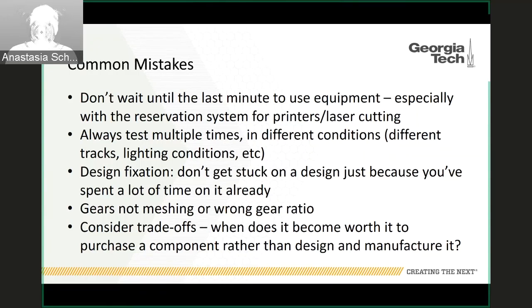And then finally, one that I really like to address is that you should always consider the trade-offs. When is it worth it to purchase a component rather than designing and manufacturing it? I've seen people try for hours to get their plastic motor coupling that they made to work. You can go on McMaster and buy a little motor coupling for like $5, and it comes with set screws and everything. Same with gears.